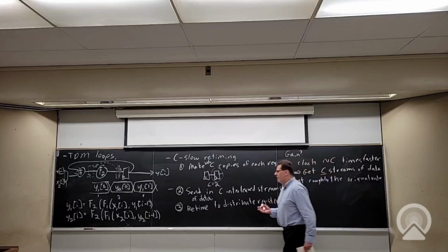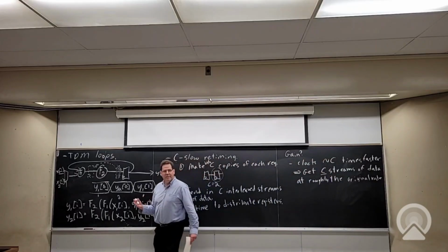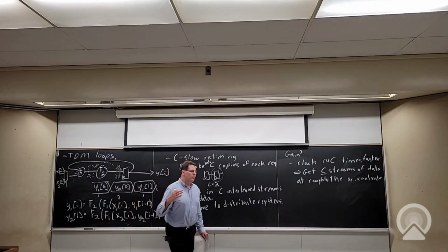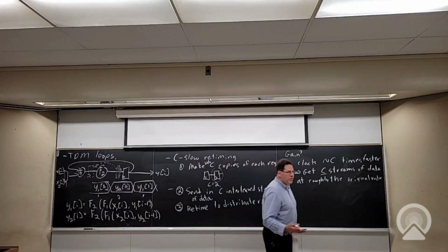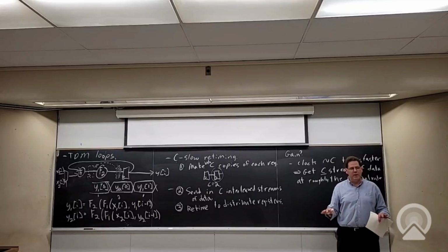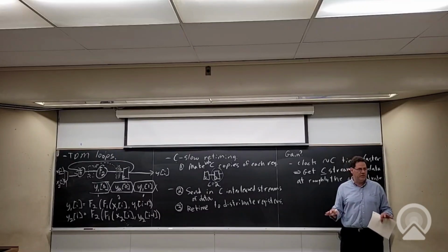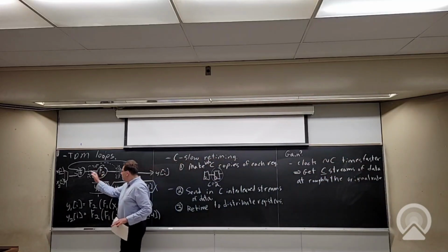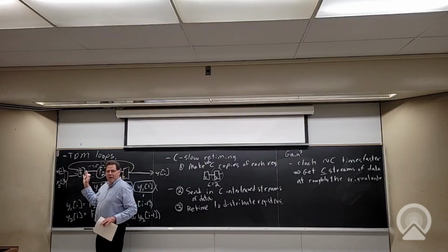The problem it has is it also doesn't know the delays very well, okay? So it also is guessing, is this a good idea or a bad idea? It'll do retiming again towards the end of placement, okay? So as it's decided where everything goes, it actually has a much better idea of what the interconnect delays are. So now it fine-tunes where your registers go because it knows the delays on each side much better, but